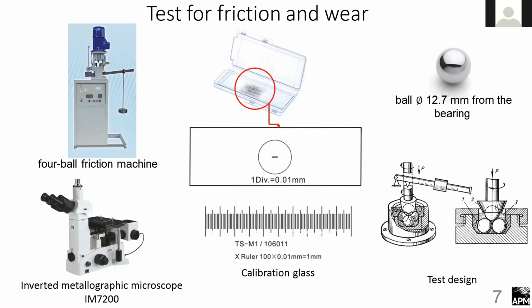Test for friction and wear of engine parts is done on the four-ball friction machine. The object in this part of the study is four balls, diameter 12.7 millimeters. Balls pass the input control in the amount of 100% for compliance with the technical conditions according to GOST 8722-2014.